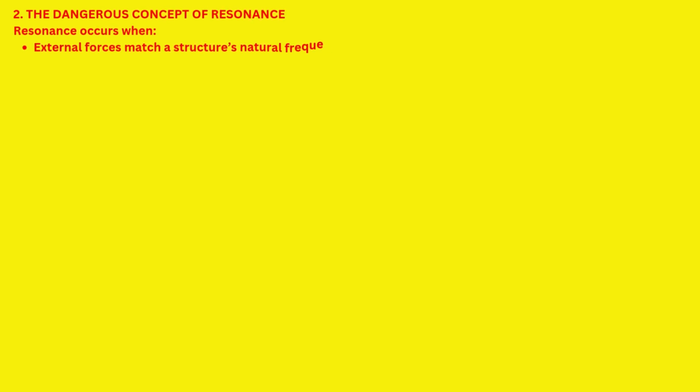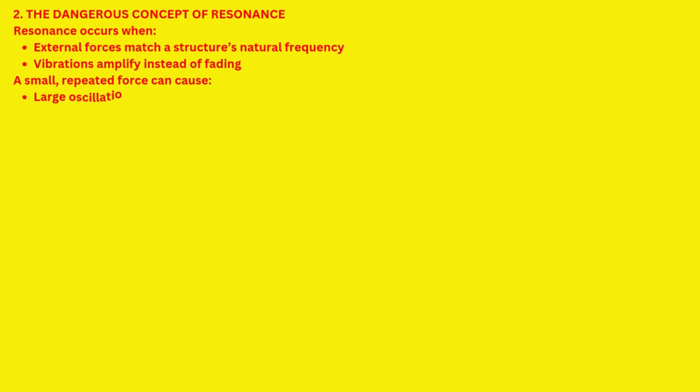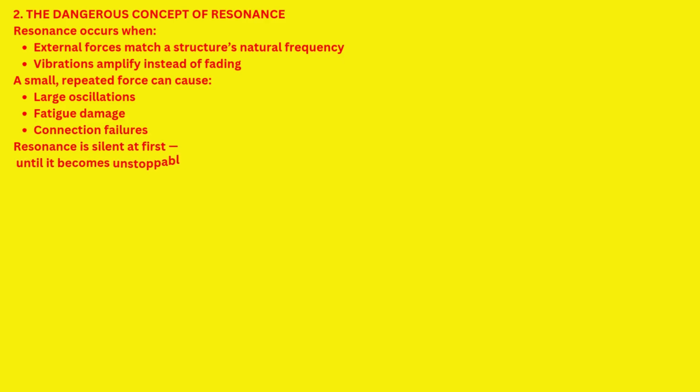2. The dangerous concept of resonance. Resonance occurs when external forces match a structure's natural frequency. Vibrations amplify instead of fading. A small repeated force can cause large oscillations, fatigue, damage, connection failures. Resonance is silent at first, until it becomes unstoppable.